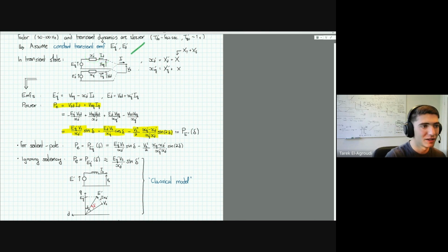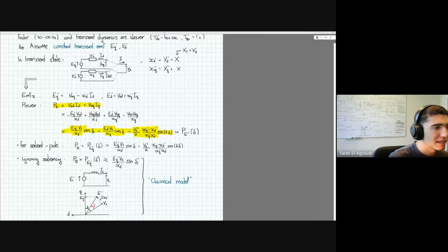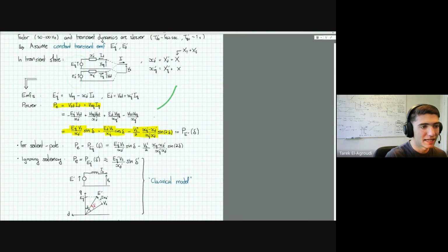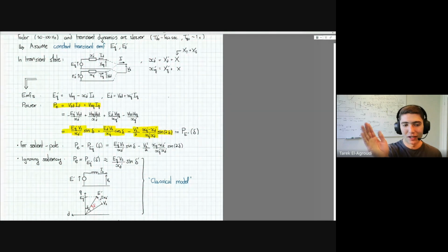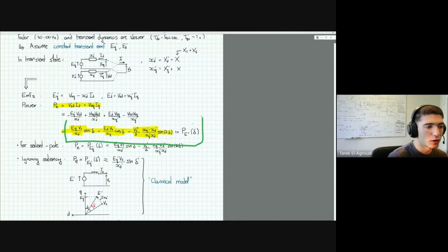It's basically including the resistance and the extra coils of the field and the damper windings. And these transient voltages, you calculate them in the same way with the phasor diagrams by just multiplying by the current and finding the power angle and all of that. But just make sure you use the transient power angle characteristic for all of this.